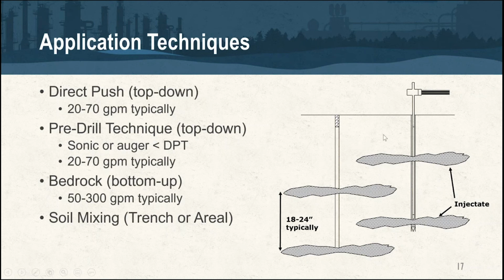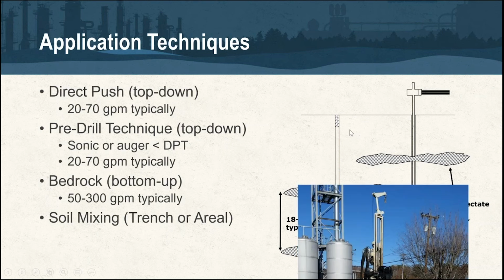it gives you an idea of, again, this spacing in an overburden is going to be usually 5 to 7.5 foot on center. Very rare occasions of 10 feet. And we stagger the vertical injection intervals usually between 1.5 and 2 feet vertically. And the injection volumes are designed so that we get some overlap between the adjacent injection locations.